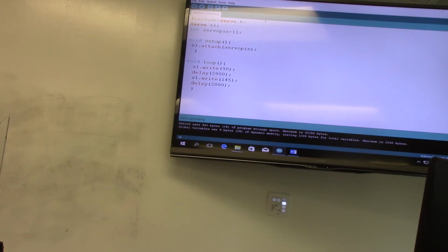Everything can be done through the program. We are just doing basics right now. So it's working on a program. Test with other joints as well. That's joint one, right? So try the others. At the beginning it's 90 degrees. Then after 2 seconds it will go to the next angle. So test each and every joint. This is the 90. This is the next one. So it's good. Test the other joints as well.